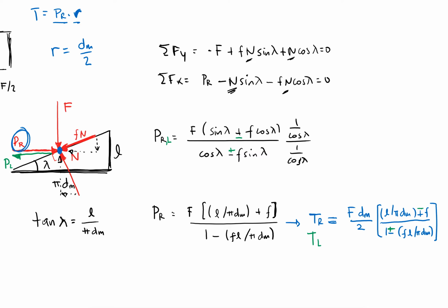Now this is important because if the lead is too high or the friction is too low, this TL would be either 0 or negative, which means that the force required to bring the load down is negative or 0. Meaning I don't need to add any extra loads.